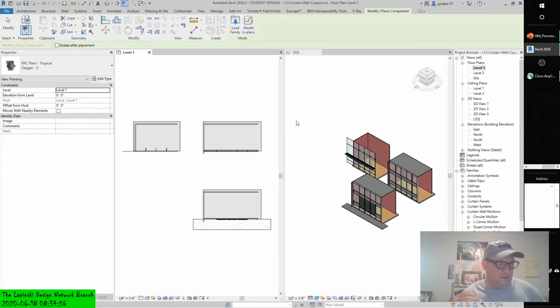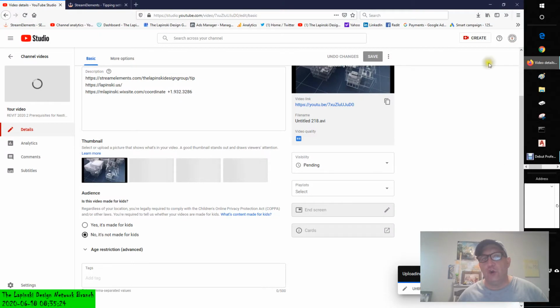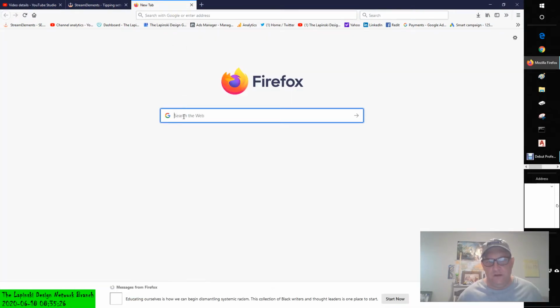They're not constrained, right? By anything other than the wall that they're embedded in. And it's a variable number. If required, you can adjust the panel geometry offset within or beyond the reference plane boundaries of the family. This is useful when creating butt glazed curtain wall assemblies.